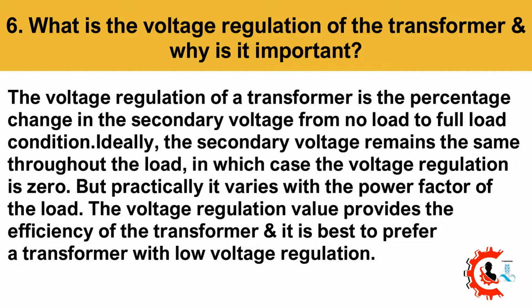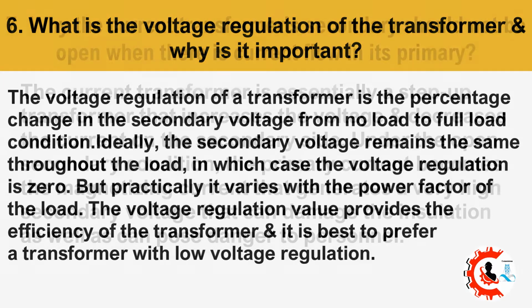6. What is the voltage regulation of the transformer and why is it important? The voltage regulation of a transformer is the percentage change in the secondary voltage from no load to full load condition. Ideally, the secondary voltage remains the same throughout the load, in which case the voltage regulation is 0. But practically it varies with the power factor of the load. The voltage regulation value provides the efficiency of the transformer, and it is best to prefer a transformer with low voltage regulation.